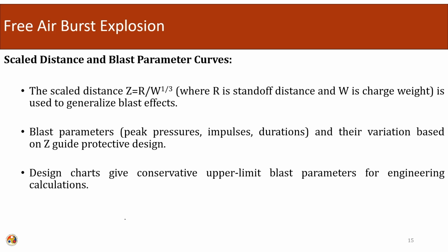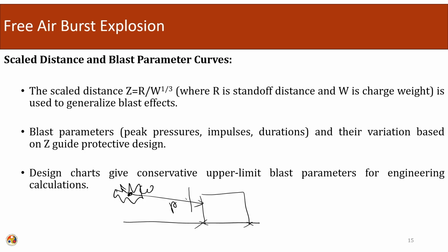Let us say we have a building out here, and a charge occurs. So, the amount of incident pressure will be a function of the weight and the distance. So, if we are measuring pressure here, there can be different combinations of W1 and R1, which will give me the same value of P.